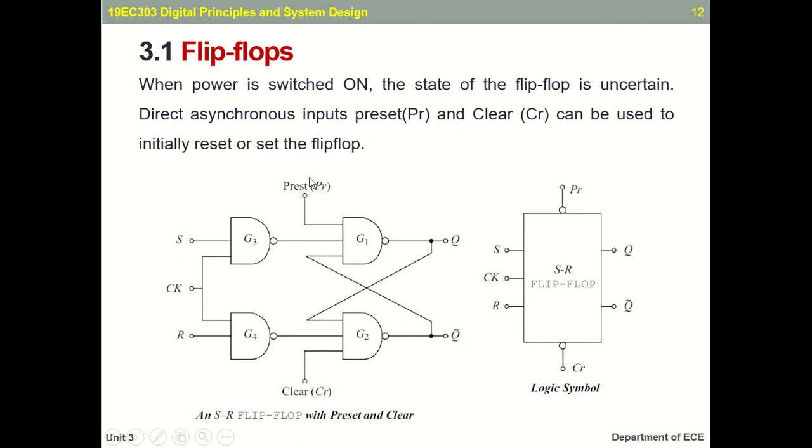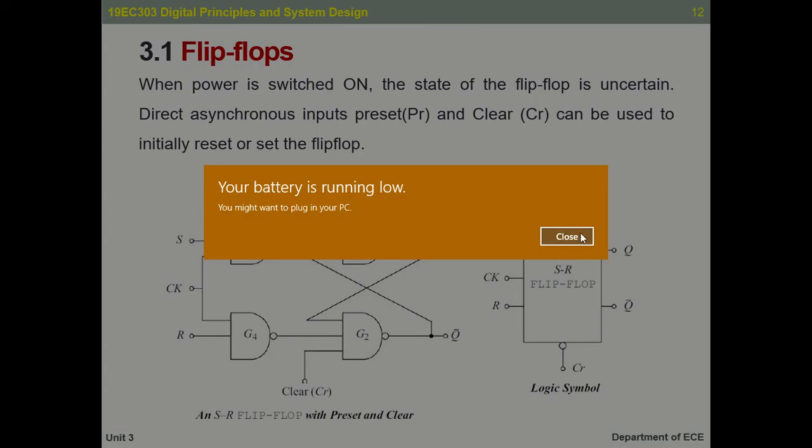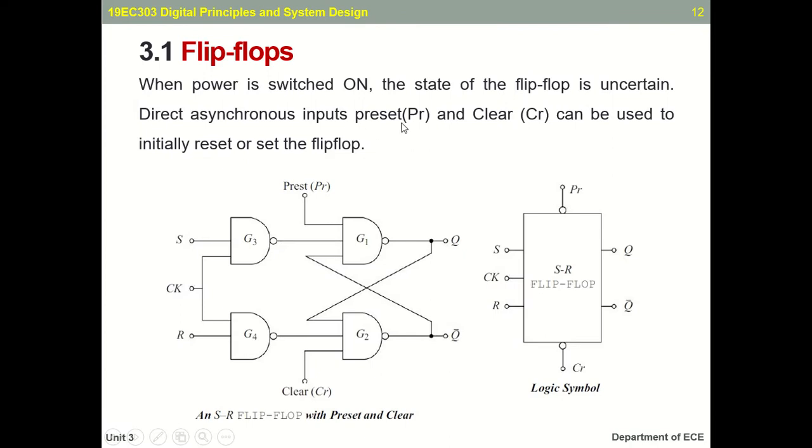Now, this is a clocked SR flip-flop, right? Instead of this clock, if you have an enable, what will happen? You will get what is called an SR latch. When the power is switched on, the state of the flip-flop is ascertained. Direct asynchronous inputs, called preset and clear (CR), can be used to initially reset or set the flip-flop.